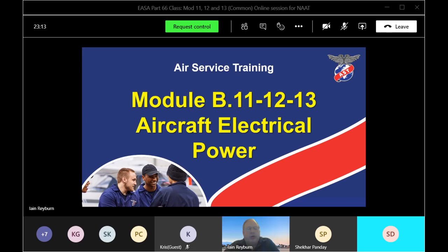And those who are B2s, you'll sometimes see the generator test point is just beside the generator contact breaker. So if you've got to do sampling, it's usually there. So, any questions on the point of regulation? No. Good. As close to the bus bar as possible, but between the generator and the contact breaker.